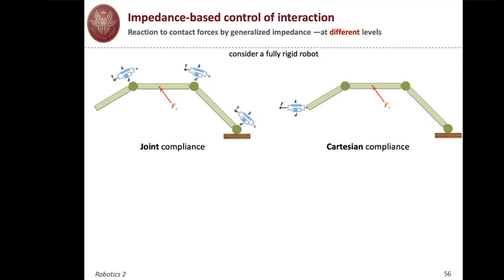At each joint we have an equivalent spring and damper attached to the desired configuration. When you're pushing the robot link or the robot body at any point, you're trying to move the structure out of the reference position for the joint compliance controller, and then you will react. So you don't need special things in this case.